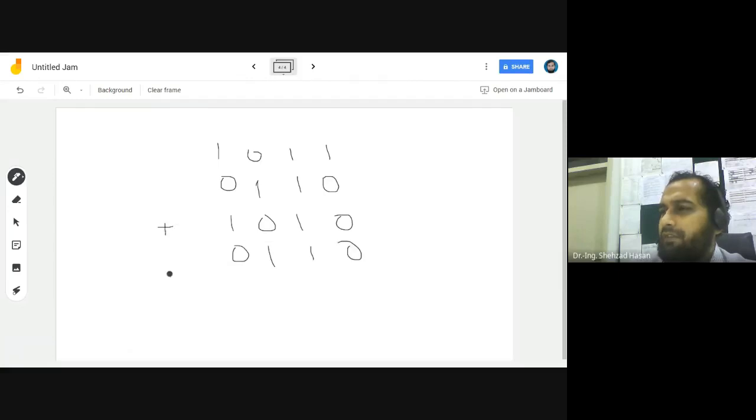Okay, so if we had to add these four numbers together, now as I've mentioned, carry save adders are mostly used for multipliers. So we get many partial results, partial products. We just have to add all those partial products and get a final answer. So it's more used over there. It's not in the same straight line, but let's just assume that this is a straight line. So 1001. What we can do is these three can be given to one full adder.